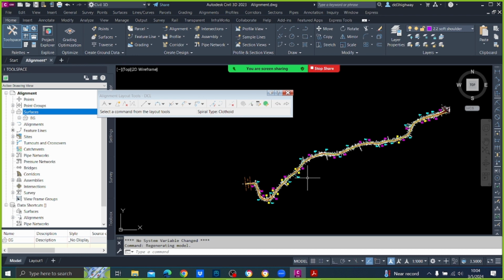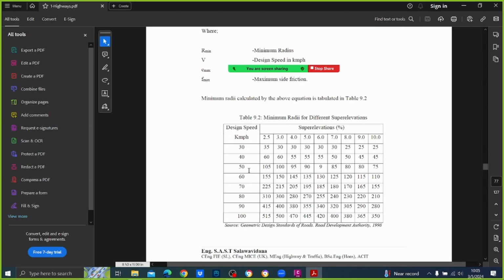If the sight distance is there, say on a straight or where the curve is large, you can go at 50 kmph, no harm. But there are some curves where you cannot go beyond 30 kmph. So here we'll decide it is 50 kmph.